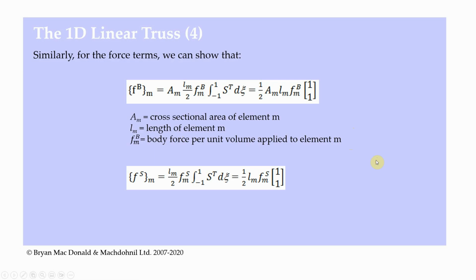And finally, the surface load, if we need to use that as well, will similarly be split between the two nodes according to this equation here, which is the surface load times the length of the element divided by 2, and that's applied equally to the two nodes within the element. When we look at more advanced elements, we won't always have this 1 and 1 here. We could have a case where we have 1/3 applied here and 2/3 applied down here, or something different. But in the case of this element, the load is distributed equally across the two nodes.